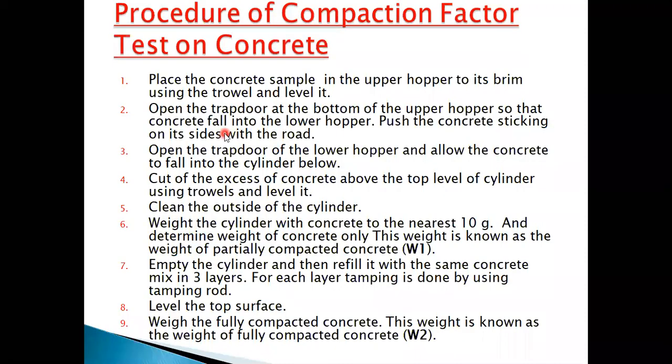Second, open the trap door at the bottom of the upper hopper so that the concrete falls into the lower hopper, and push the concrete sticking on the sides with the end of the rod.